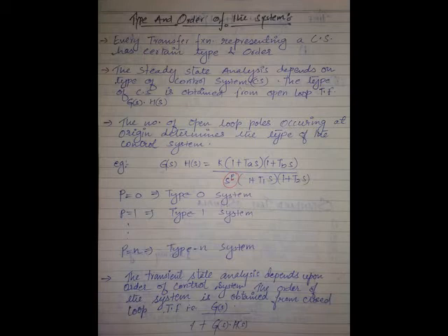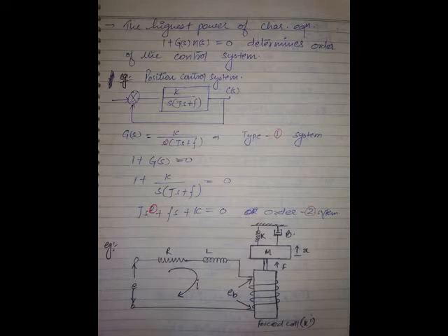This is potentiometer A. Now, the main aim of this control system is to transfer the input position of the shaft to the load. So, this is connected to the wiper contact of the first potentiometer. As this is displaced, the wiper also will move. It produces a voltage. This voltage, we send it through a servo amplifier.